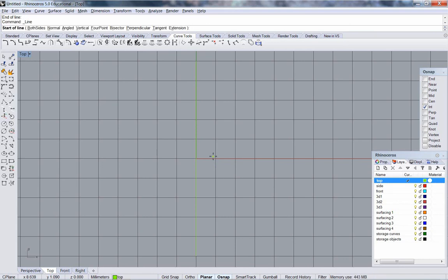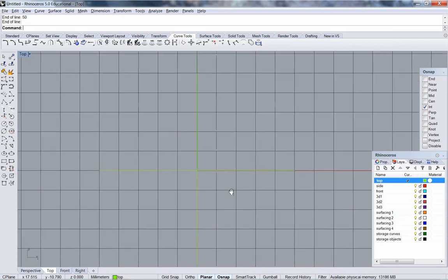Repeat the command, enter, 0 enter, both sides option, 50 millimeters, canceled out. Start a line 0, both sides option. I did that with the keyboard. Constrain length 50 millimeters. Hold down Shift key and click.